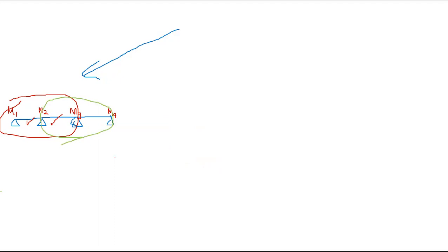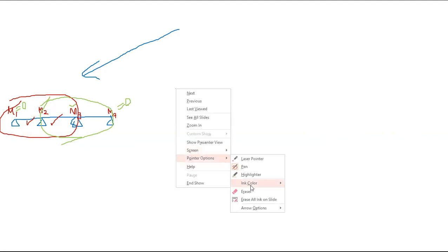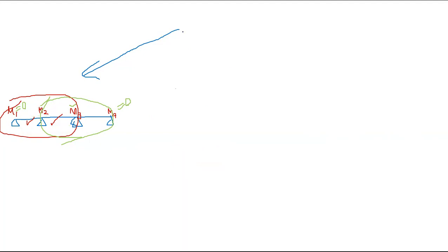Similar to what we did, if you have any settlements, you can even compensate with this equation. What we know is at the ends M1 and M4 are 0. So you will have two equations and two unknowns, M2 and M3, so you can solve it. When the number of spans increases, the computational effort will be high.